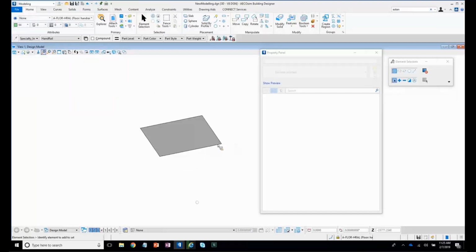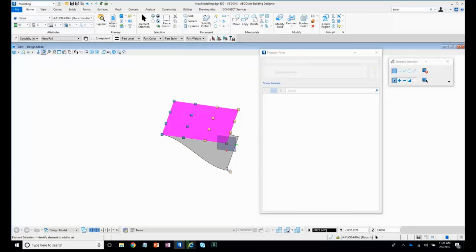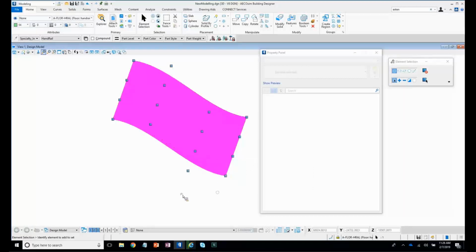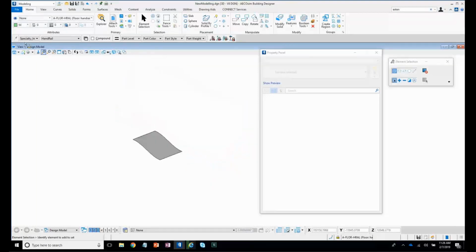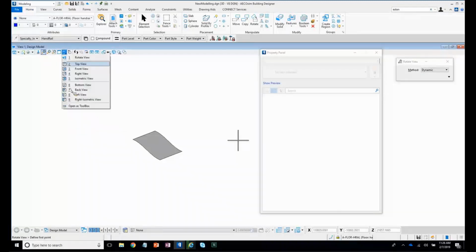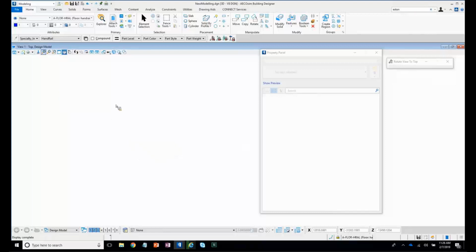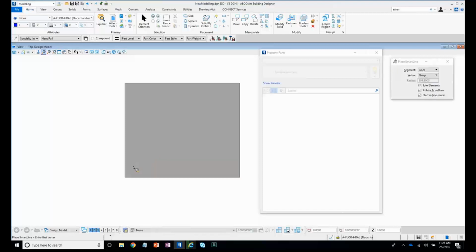Okay, so let's just quickly build a surface. Oops, it's not part and family set there, but it doesn't matter. And what we've got is these handles when I select it. So if I use the control key, I can grab these handles and just bend that down like that. I'll bring it up a bit actually, just so it's not such a steep decline. There we go. Okay. Let's change the color quickly, and in plan, we'll say top view. Okay, let's say we wanted that railing run to look something a little like this. We wanted the railing to follow that down.